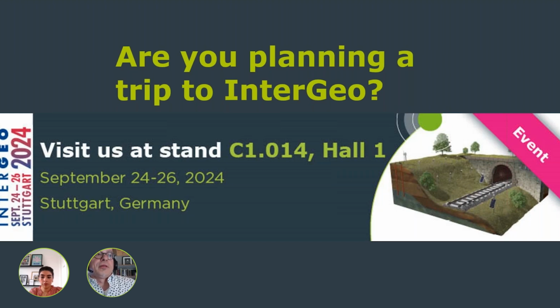In general, yes, it's only the signal type, whether we can read the signal type, like vibrating wire or potentiometric, millivolt, volt, or even the digital signals from weather stations or in-place inclinometers or something like this. We would just have to figure out whether we can read the signal. And then, of course, we may need to provide a certain plug to plug into our unit. But yes, customers can also provide their own sensors, and they can usually be connected to our nodes of the specific sensor type or signal type.